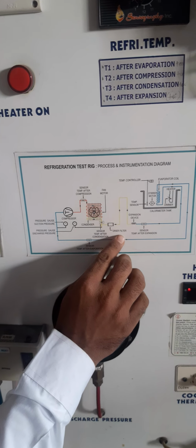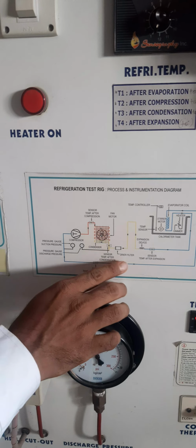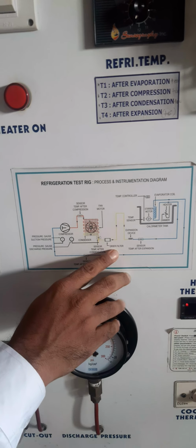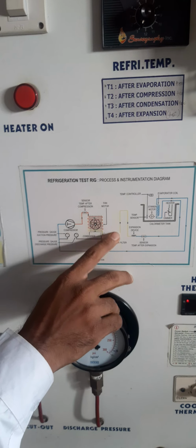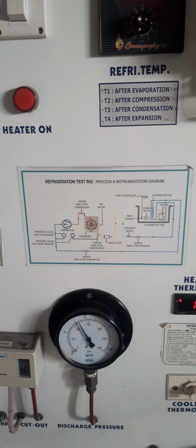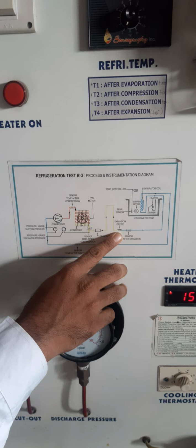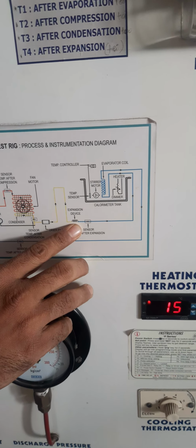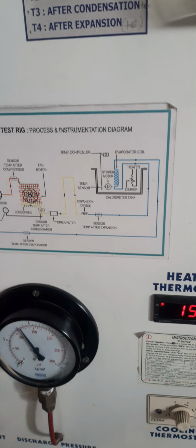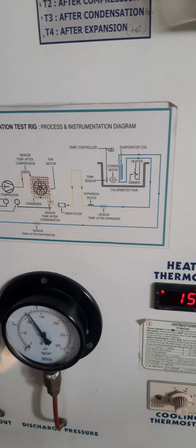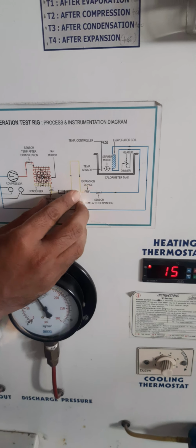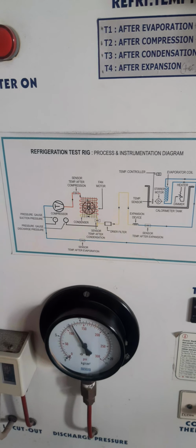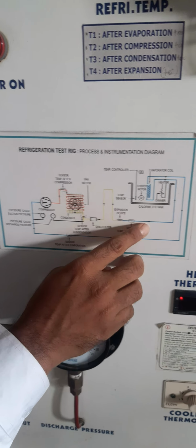After that it is allowed to pass through the dryer, where it removes whatever moisture content or dust particles are present in the refrigerant. After that it enters the expansion device. It will get evaporated slightly over here, then pressure and temperature are reduced, and the velocity of the refrigerant is increased, and that's why it gets evaporated. The refrigerant coming from the bigger diameter pipe enters a small diameter pipe, and that's why it gets evaporated. After that it enters the